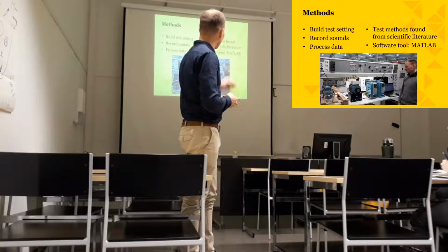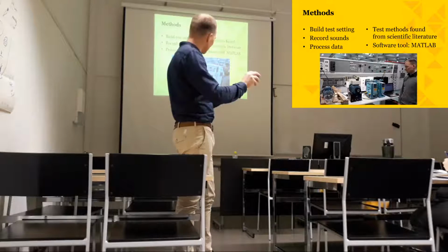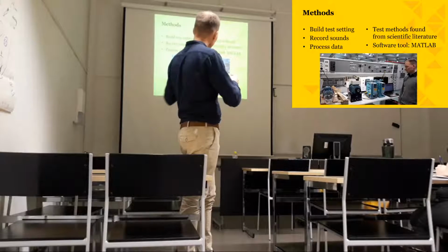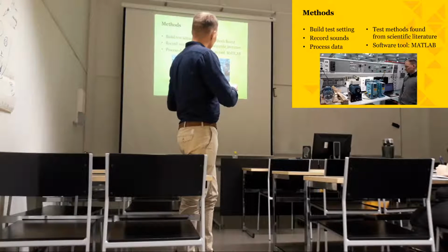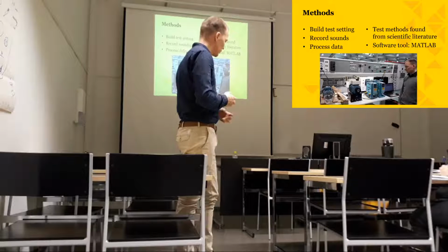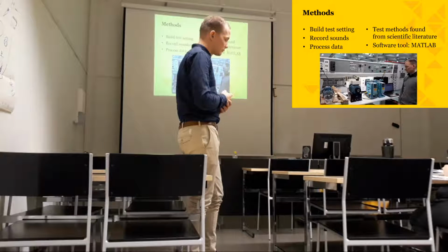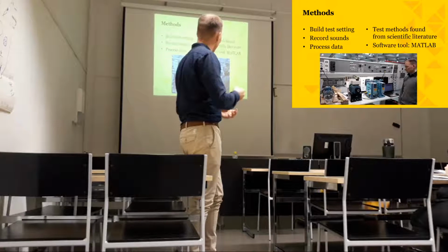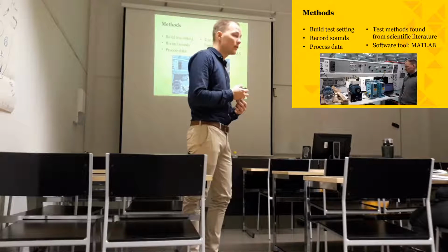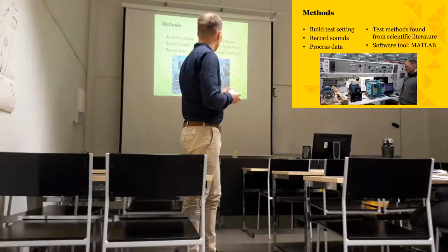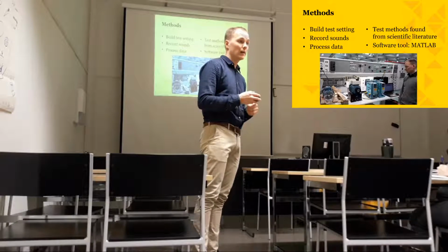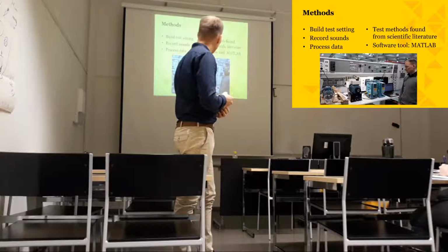Then I got two frequency converters, and all the motors and frequency converters were as similar as possible to eliminate all the things that could interfere with the experiment. Then I recorded the sounds using the methods we have learned in this course, and then I processed the data. I found some methods from the literature, and I used MATLAB to implement them.